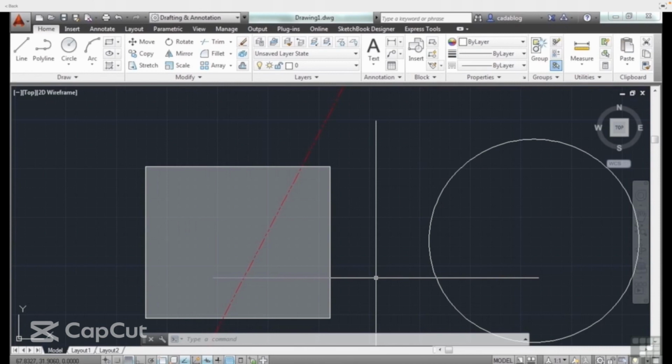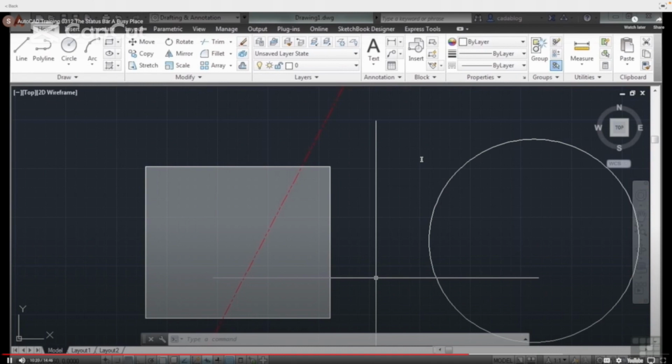Then you tell the annotation text through AutoCAD settings that, hey, I have text here, and scale up or down the annotation to whatever scale it is just to fit. And you define a paper size so that when you print it out, it's going to be 3/16 of an inch high or whatever it is you want it to be. So that's a real nice feature.